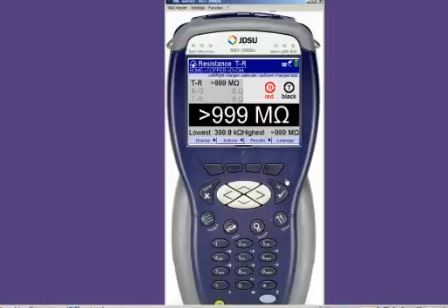If it's nothing more than a battery, how much battery does your ohmmeter put out, Jeff? Well, in this mode right here, I put out 30 volts DC. Right. If you look under F4, it lines up with the word that says leakage. If you press F4, the lightning bolt appears on the screen. That's an indication that the 30 volts has gone to 120 volts. Now, the 120 volts is a current limited supply. All that means is it cannot hurt you. It'll tickle you well. If you're grounded good, you'll certainly know it's there, but it's not going to hurt you or harm you. The thought being the 120 will look harder for a shorter ground than the 30.